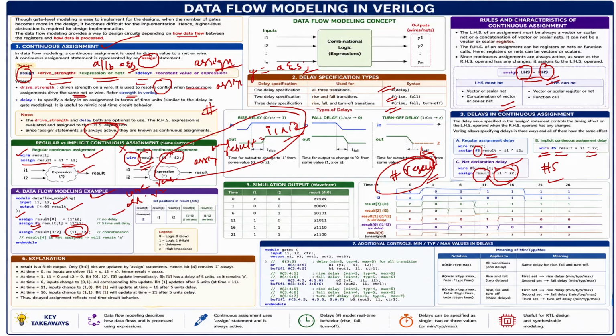See here, I am taking the 4-bit result here. Result 0, result 1, result 2, comma 3. So then the fourth result is not there, then you will get the high impedance value. So you are giving inputs unknown values. Always you are getting an unknown value because the fourth value is unknown, high impedance value.